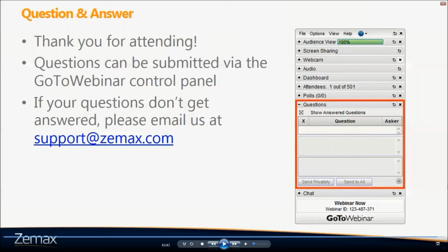Okay, so there's a question about the filter string I used at the very end. It is H18. I was a little unsure where you determined that. Very good catch. I determined that from memory because I've used the filter strings enough that I know which one to use. When you are first using the filter strings, I'd recommend bookmarking the section of the help files that lists all the filter strings, or you could print it out. And so H18 just means hit object 18. And there are a lot of other filter strings that are structured very similarly.